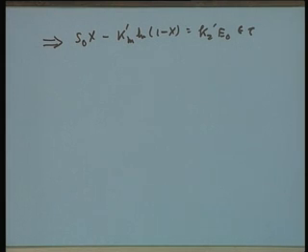While in the case of a stirred batch reactor, the epsilon is taken to be 1. That means, the volume of the reactor occupied by the enzyme preparation is negligible compared to the total reactor volume. Whereas, in the case of a packed bed, a significant proportion of the reactor is occupied by the enzyme preparation.